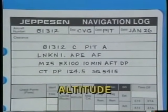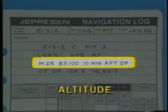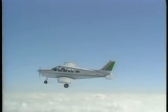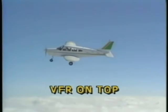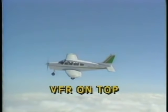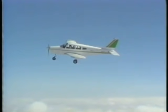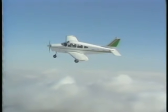The next item is the assigned altitude. "Maintain 2,500, expect 10,000 10 minutes after departure." You will always get an assigned altitude even if you've been cleared as filed. However, instead of a specific altitude, you can request VFR on top. This allows you to remain on an IFR flight plan, but lets you fly at any VFR cruising altitude, from the minimum IFR altitude up to but not including 18,000 feet, as long as you're able to stay in VFR conditions.